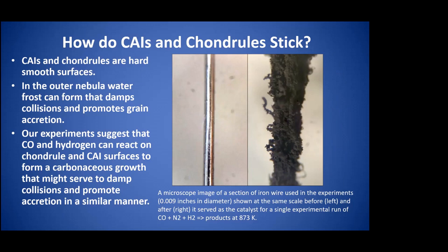Thanks. Well, like I said, the problem basically is you don't want to talk about this as Fischer-Tropsch reactions, because the normal chemist will say this isn't Fischer-Tropsch. And it's pretty obvious because the active surface is changing over time. And as this carbonaceous material is deposited, the rate of reaction goes up, not only because the material itself is a better catalyst, but because the surface area increases.